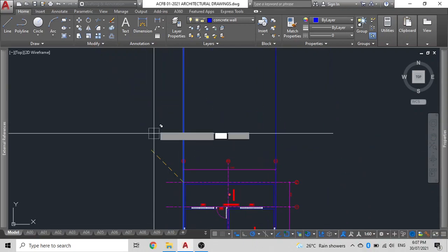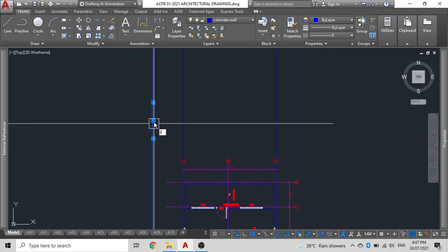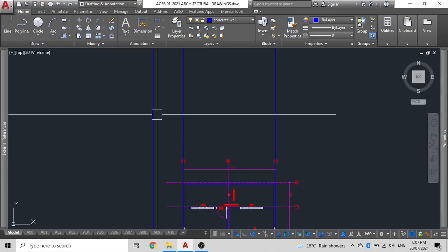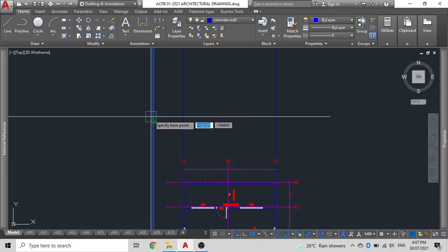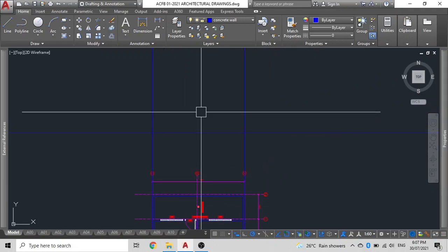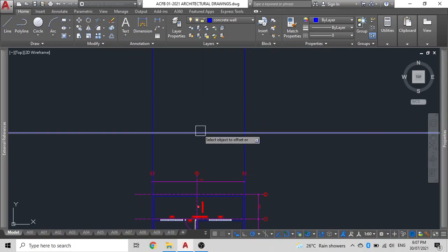That's one there. We'll just rotate this line. We don't have to create another X line unnecessarily. Or X line is construction line. Then we'll do an offset of 750 millimeters from this line. Now this line is our ground line.